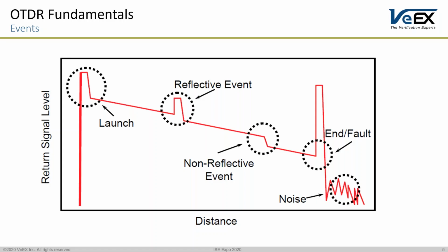The trace will provide a downward slope from left to right. The slope factor is determined by the fiber's vendor attenuation coefficient. So if you're splicing two different vendors together, you may see a slight variation in slope, and this will skew your loss measurement. This is why you would do a bidirectional test and determine a real, true, actual loss at any event.